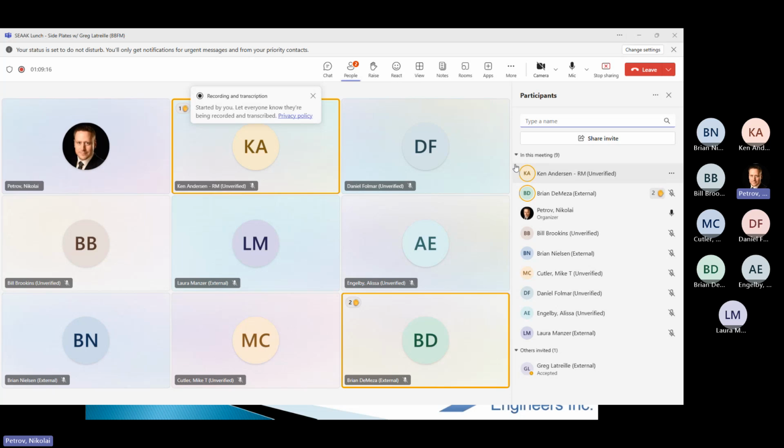There are rules of thumb, like three stories, 1,000 square feet, or less than that. Every time we try to set that kind of rule, there are situations where it's clear it's probably going to be a good fit, and then there are other ones where we're not sure. So what we do is approach them and let them look at it, and they basically will tell us. But certainly a single story building probably is not going to be a good candidate for SidePlate. Two stories, maybe, it depends on how big, but three stories and up, if you're going to do moment frames, it's definitely worth looking into SidePlate.